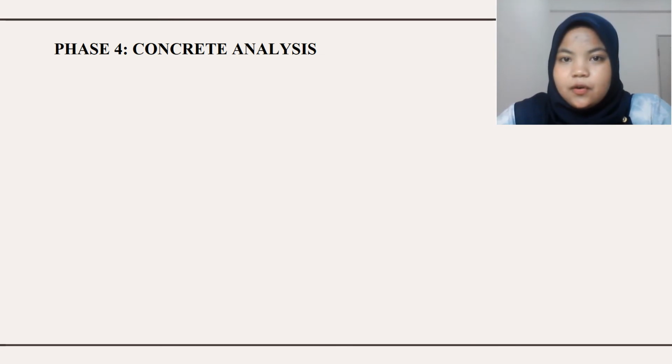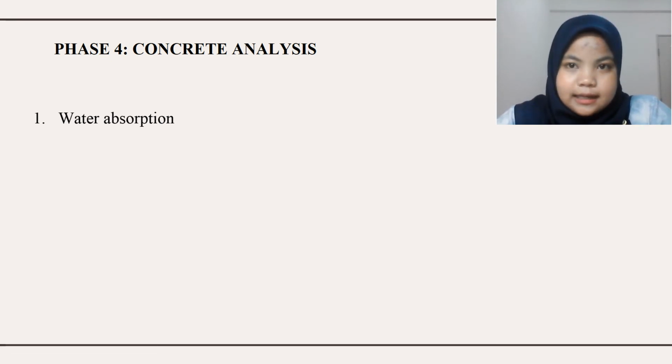Lastly, Phase 4 consists of 3 analyses. The first one is water absorption. This test determines the absorption rate, which is the sorptivity of both the outer and inner concrete surface. It is water absorption testing of hydraulic cement concrete using vacuum saturation.